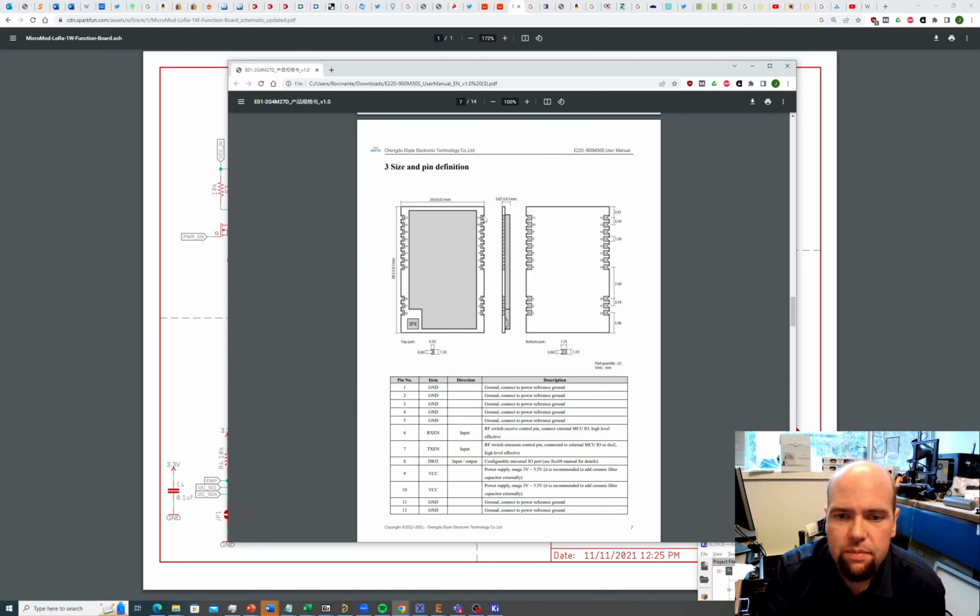To do that, we're going to be building pads that extend out beyond the edges of these pins. You see the dimensions here are a little wonky, right? They're 24 millimeters across, 38.5 down. But more importantly, the pins are a little weird. This first pin is 2.61 millimeters from the edge. And then they're 2.54 spacing, which is fairly standard. And then they're 7.60 spaced here. That almost feels wrong. It feels like it should be 7.62 spaced, which would be 0.3 inches. Maybe that's an error in the data sheet. I don't know. But if the data sheet says 7.6, I'd probably go with 7.6. It could be somebody did a rounding error, but this is a weird footprint.